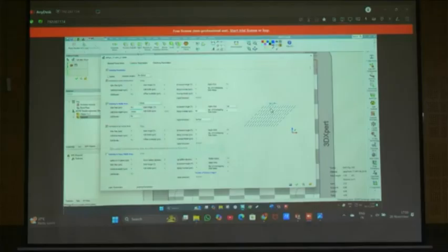And the side step means the distance between the hatch spacing. You can see these lines, right? Each hatch is there, that will go very fast actually during the printing, you can see how it is printing. So that is the distance between hatching. Suppose if you want to change this 50 to 45, we can change it. And strips, by default it is hexagonal, so I can keep it as rectangular, or alternated, meaning chessboard.